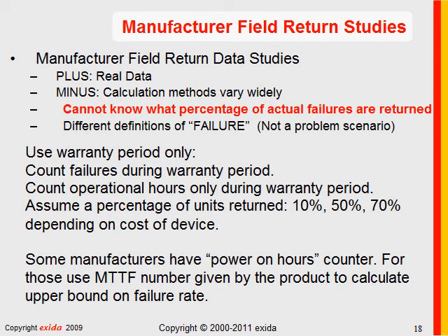However, I find this power on hours counter to be a valuable piece of information that has helped improve quality of manufacturer field return studies quite a bit. By the way, it was a detailed review of the power on hours counter that allowed us to come up with a very accurate estimate of the time period between shipment and startup. And we found, based on 2 or 3 studies of the power on counters, that 6 months is a very good estimate for process industry applications.